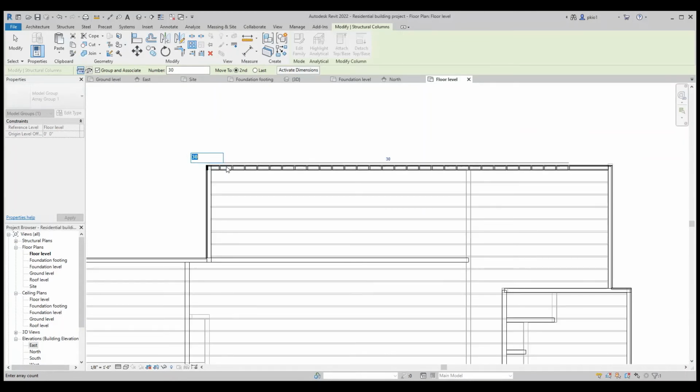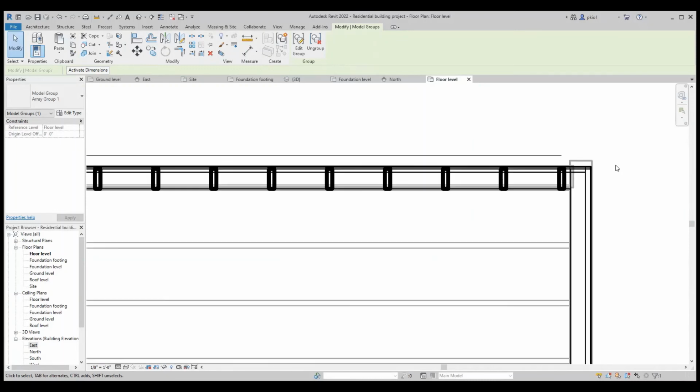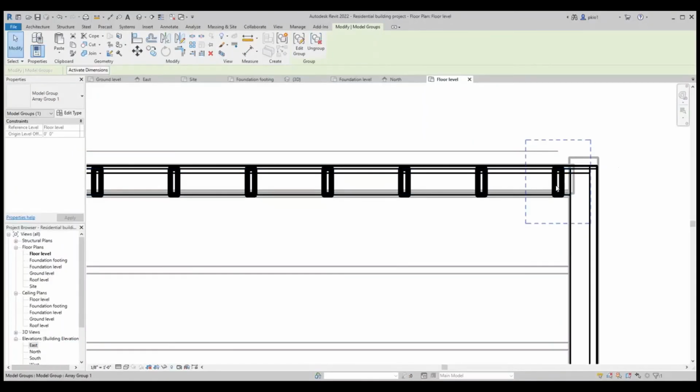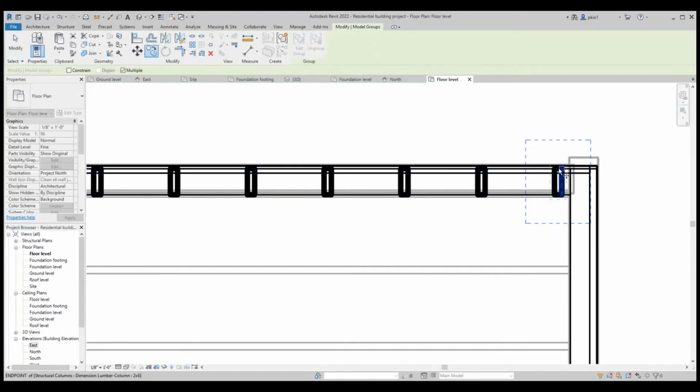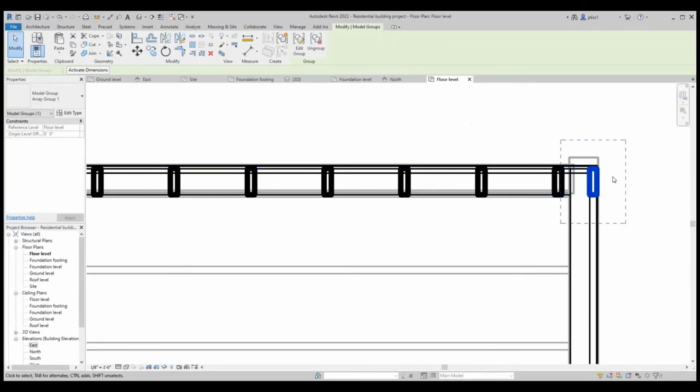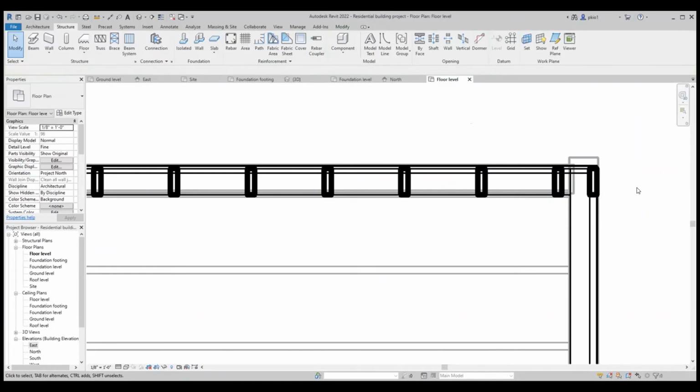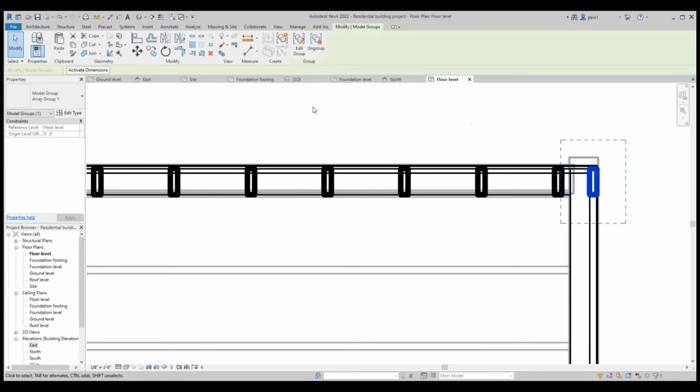It looks like we need more, maybe 33. And so we have 33 studs on this wall. Now for the edge, we might need to copy this and place it at the edge. At the edges, we can either have a regular corner or a California corner. The regular corner will be 2 studs in a corner, which I will draw.